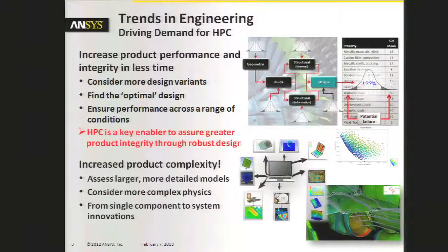So the more part of this, back in the 90s, I was in the HVAC industry, and it was common to apply CAE tools to run a few design points in the V&D stages, late in the product development cycle. Whereas these days, you find CAE moving forward, doing multiple point designs or Six Sigma, DOE, etc. So do it earlier, do a lot more of it. Don't optimize to a single operating condition, but really hone the design, make sure it works across a wide range of conditions. Essentially apply virtual product development, make sure the design's going to work before you even build the first prototype.